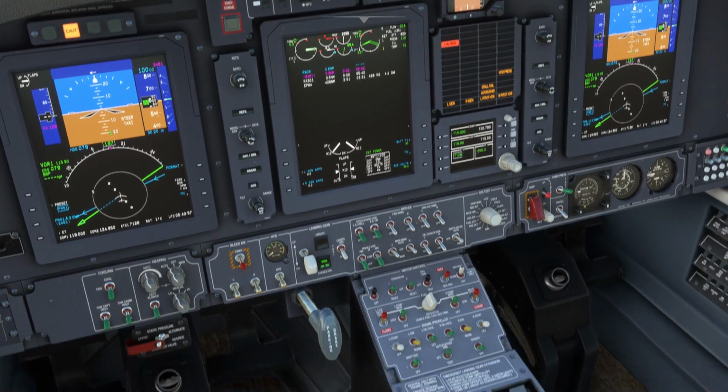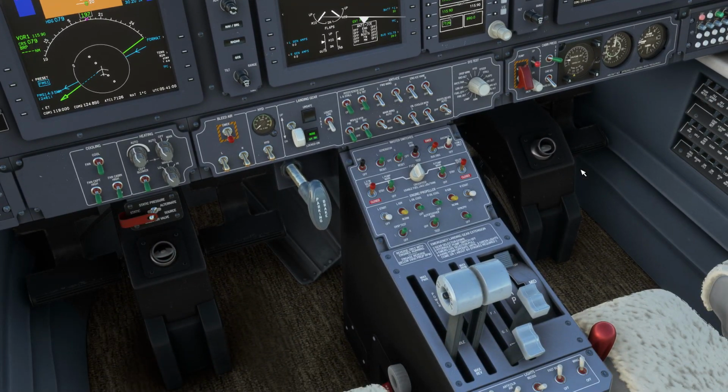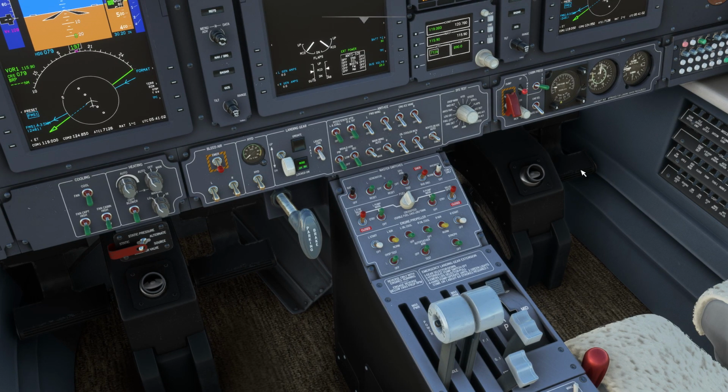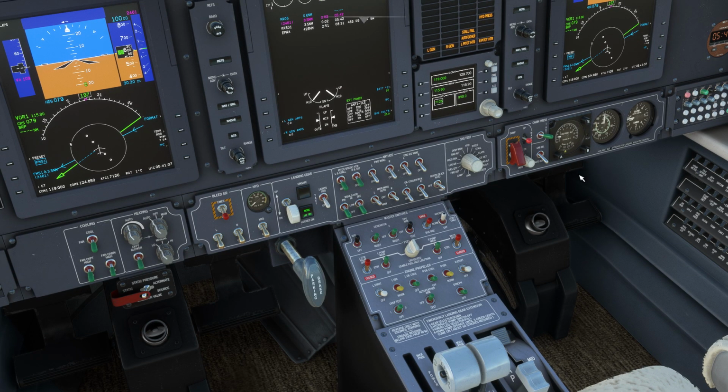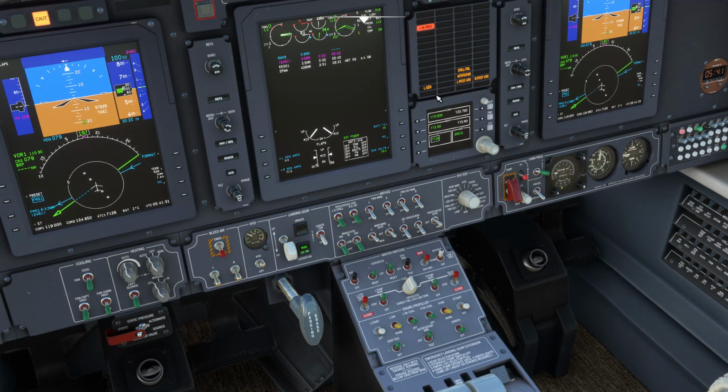Fantastic. So when we will be starting the next engine without GPU, at that moment we want the generator reset and to on. And that's our voltage. That's the right engine generating. So we do have that one checked. Bus voltage is checked. Hydraulic pump is on. Hydraulic pressure light. We do not have the hydraulic pressure light anymore.